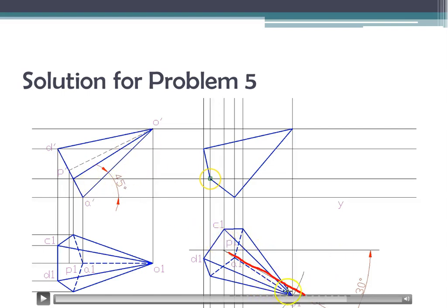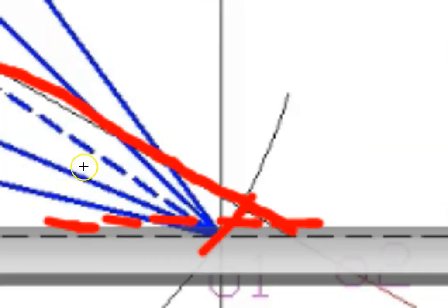At the point where it becomes 65 mm, we draw a locus line like that, and on that locus line we take this distance, the actual projected length of the axis, which can be taken from the other view. With this point as center, we cut an arc through this locus and join that O to this point to give the current position of the top view.